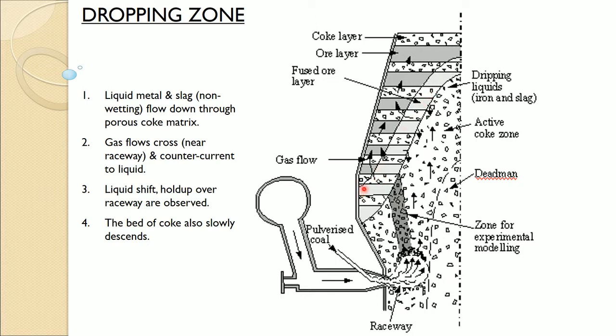and as you know, the cohesive zone is a mushy zone where liquid iron and slag are in semi-solid form and start melting in the lower boundary of that. So, liquid and slag drop down, gases are going up, and this cohesive zone gives big resistance to the gases. So, very high pressure drop in this region.